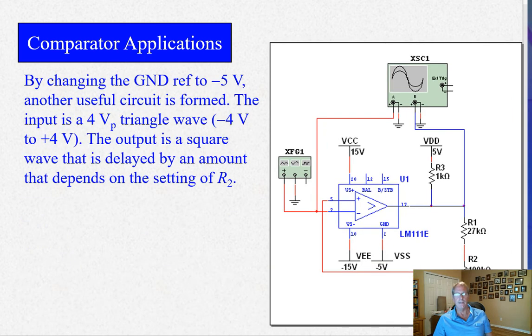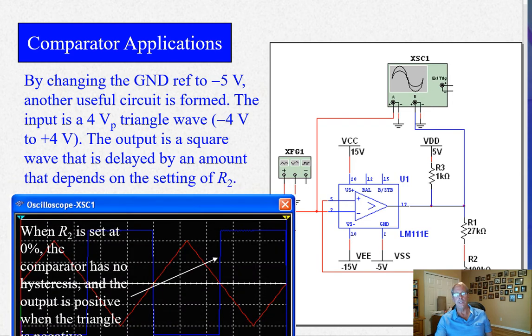Take a look at the LM311 data sheet on digikey.com or anywhere you can find it. Have a look at it. You'll see there are some great circuit examples, probably from Texas Instruments, on the use of the LM311 comparator. There's also an LM339 comparator, very similar. I think it has a little higher output voltage capability, but it is also open collector.